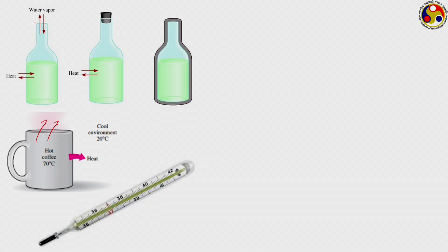A standard medical thermometer. Now, what kind of system is this? Here you have to choose the system boundary first. That is important, because in the previous examples a proper boundary was given, but here you have to choose the boundary. So, what can be your choice for the boundary? Here you have the capillary tube through which the mercury, or whatever thermometric fluid you are using, is present. So, that itself can be taken as the boundary. Accordingly, your choice of boundary can be this yellow capillary, forming this particular surface, which encompasses only the thermometric fluid part.